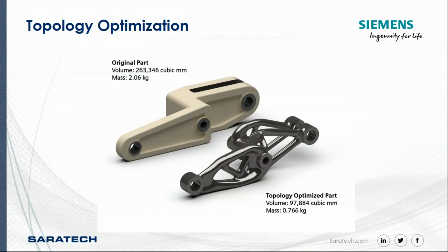So I talked about topology optimization. For those of you that aren't familiar with topology optimization, the way this works is you basically hand the system a bunch of inputs. So you give it a design volume or design space that it can create a part inside of. You give it some keep in areas, some keep out areas. You give it some loads, so it can use CAE under the hood, and you tell it what the material is you want to build the final part out of.